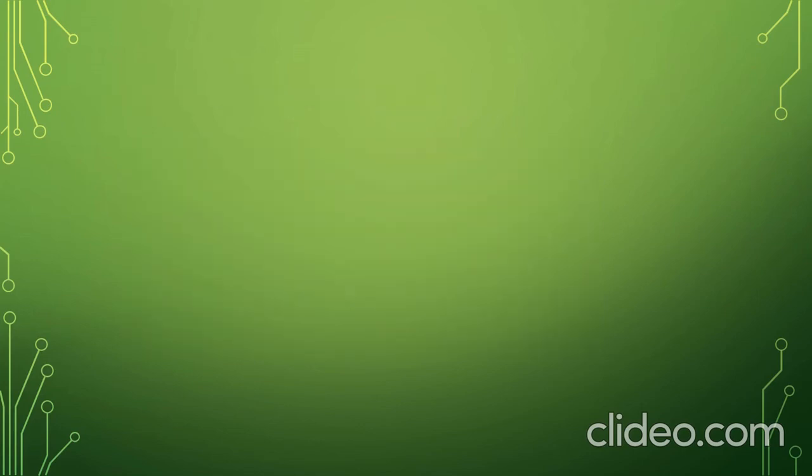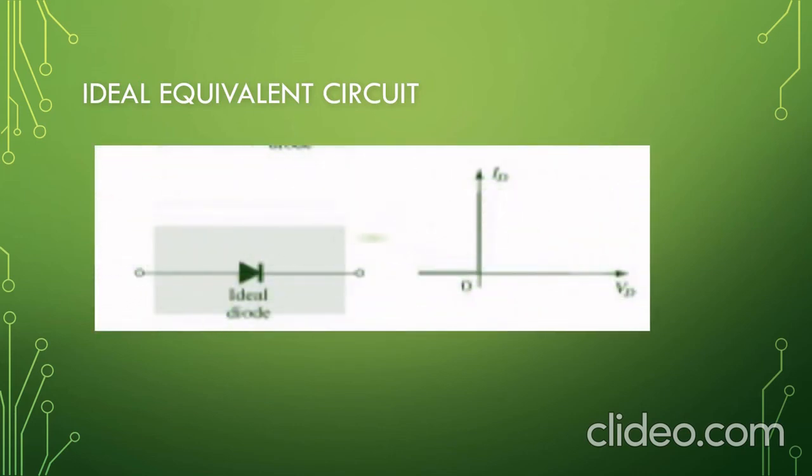The next diode equivalent circuit is the ideal equivalent circuit. Now, the R resistance has been removed from the equivalent circuit. Let us take the analysis a step further. That means the 0.7 volt level can often be ignored in comparison to the applied voltage level. In this case, the equivalent circuit is reduced to that of an ideal diode only, and this is the ideal diode. Here we neglect the Vk voltage and the R resistance also, and this is the graphical representation of the Vd versus Id graph.